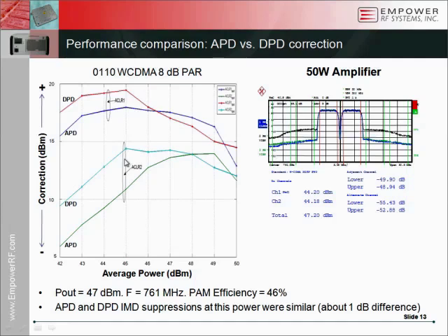Yeah, as a designer, we always like transistors in a moderate size. I think when you get to very large transistors, you do have effects that come into play that are more difficult. Asymmetrical Dohertys are becoming more common, so using different size transistors for main and peaking is becoming more common. So yes, you have to play with your architecture both at the system and the circuit level in order to achieve the best results, in my opinion. Does that answer your question?